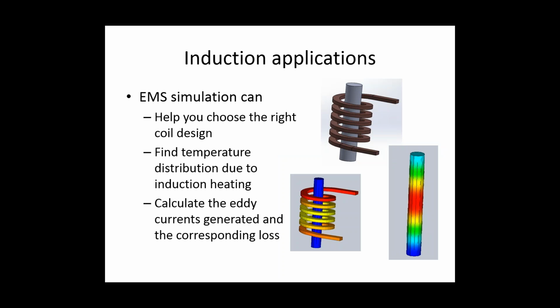For induction applications, EMS can actually help you to choose the right coil design that can serve your need. It will also compute the temperature distribution due to inductive heating, and also compute the eddy currents generated and the corresponding losses which result in heat.